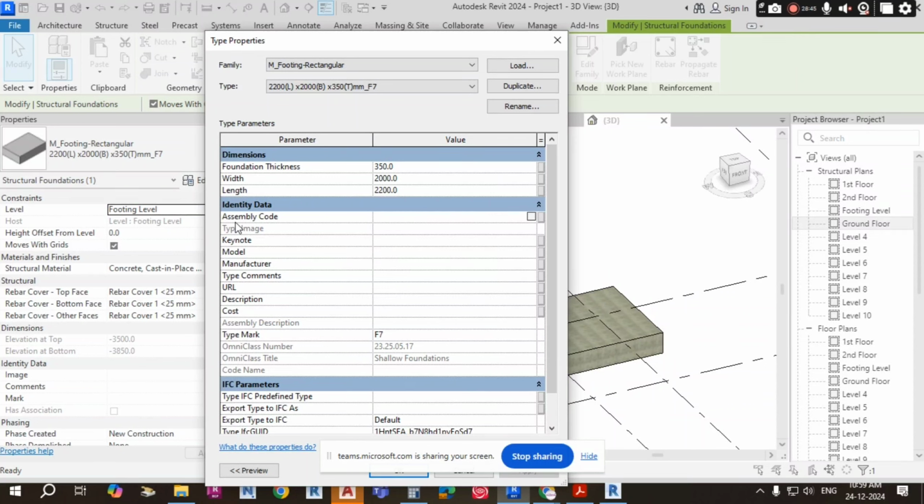Right now, think that my project is going to be worked out with LOD 300. 350 also we will develop, and later we will develop 400 also, because here you are working level-wise. Initially you placed the model, and you gave some documentation and dimensions, which is LOD 200. Now you are giving some information, this comes under LOD 300. And if you are showing some color of that footing with material, it is 400. And if you are giving some scheduling and quantities, then it is 350. Like that it will become.